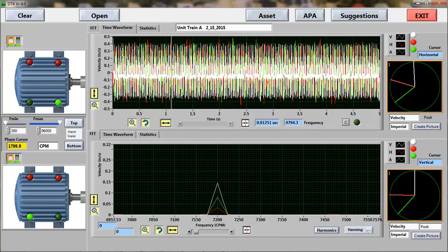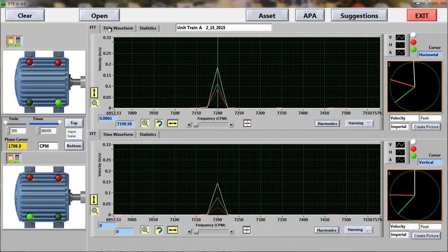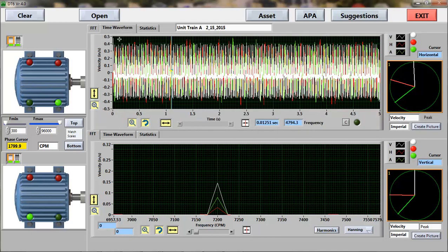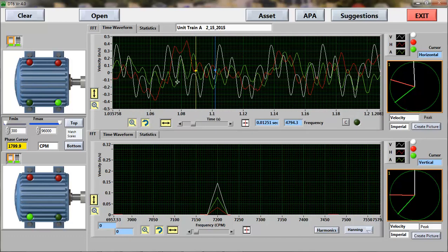Turn that off. The time domain is a long duration, so what we generally are looking for are long-term trends. If the whole thing is not centered on zero, say it's all shifted up, you might have some kind of a rub going on or constraint. You can see various time bits of information, jolts and variations that happen in time, that you simply cannot see in a frequency domain. Here again it's high resolution, so you're going to be zooming in an awful lot. We want to zoom in and take a look at, say, what's going on in this region.